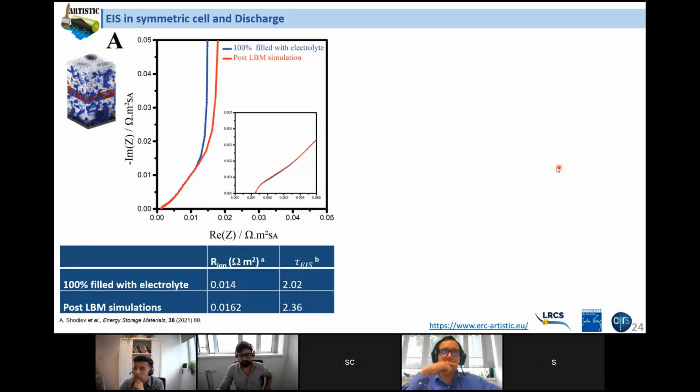Yeah, so when you have uncalendered electrodes, you have a bigger pore size and bigger porosity. Overall, it goes very fast. But while calendering goes on, the pore size distribution becomes smaller, right? And then porosity decreases by at least half. So the electrolyte goes slower.